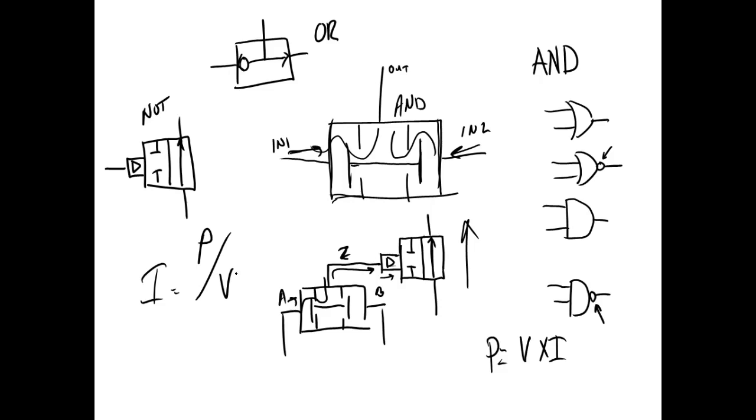If a magnetic field cuts another conductor, it will try to induce a voltage into that conductor. The amount of voltage it induces depends on the strength of the magnetic field plus the number of loops in the conductor. Those conductors don't loop. Those conductors are straight. So the amount of EMF you get depends on how far they're apart. So that's why they separate them so far.